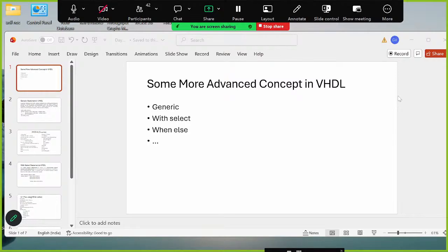Okay. So, yesterday we were discussing finite state machines, where I took an example of a simple traffic light controller. I implemented it first with the help of a Moore machine, in which the output is only a function of the state of the flip-flops, whereas when I implemented it with the Mealy machine by introducing a sensor as an input, the output depends upon the input as well as the states of the machine.